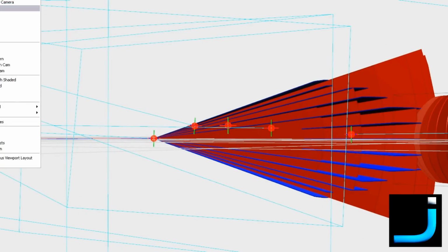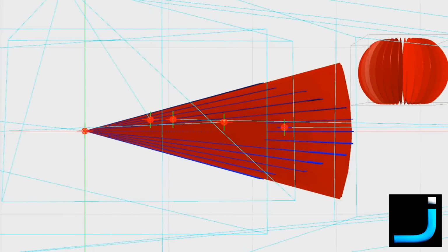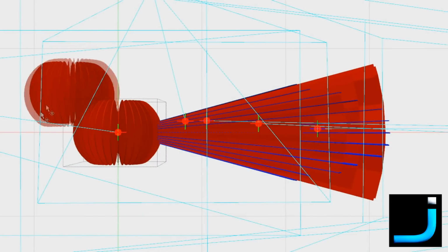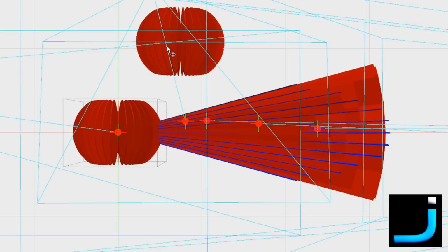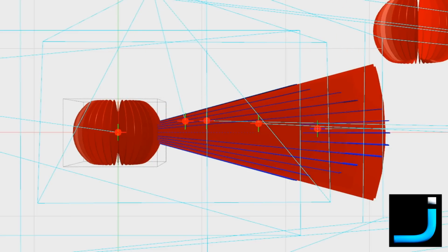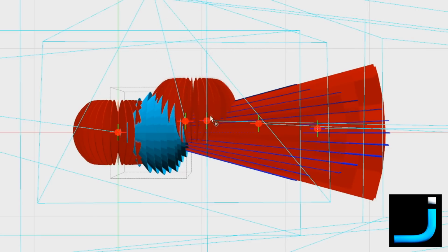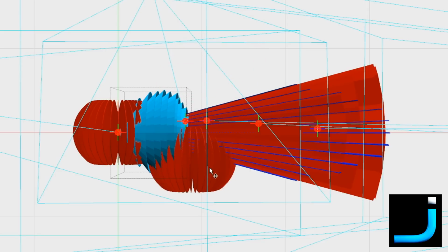So let's go back to the front view, and let's turn on your plane here. To compare, we've got the rubber ducky, which gets you to about here. However, the benefit is we can fly right behind ourselves if we want and we'll still be in range, assuming we're not too far away. Omnidirectional. And then we have our circular, which we'll do next, which we can get a little bit further. And remember, it's less sensitive to your orientation of the plane, so it's a little bit more of a consistent range.